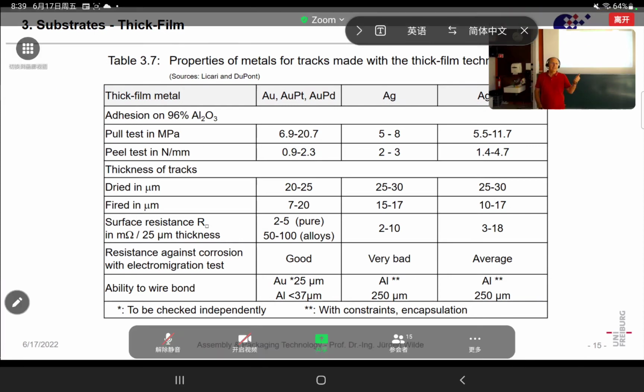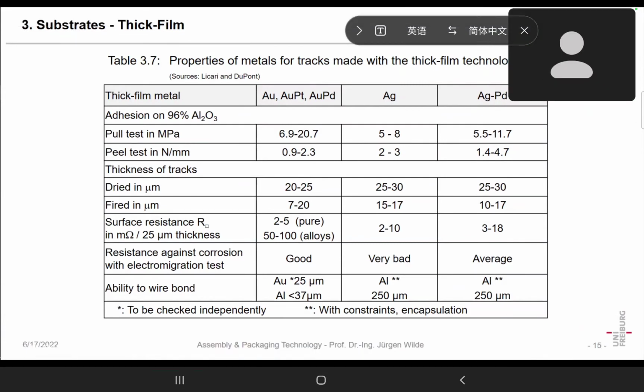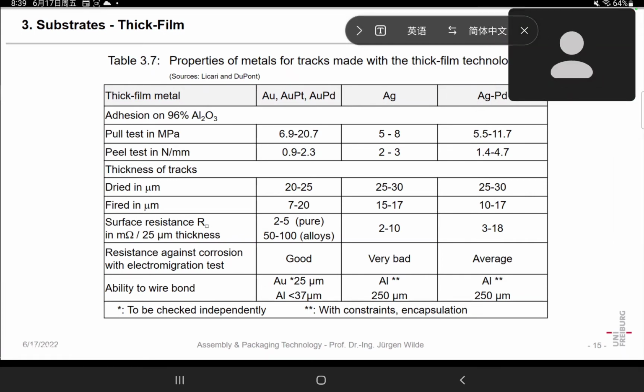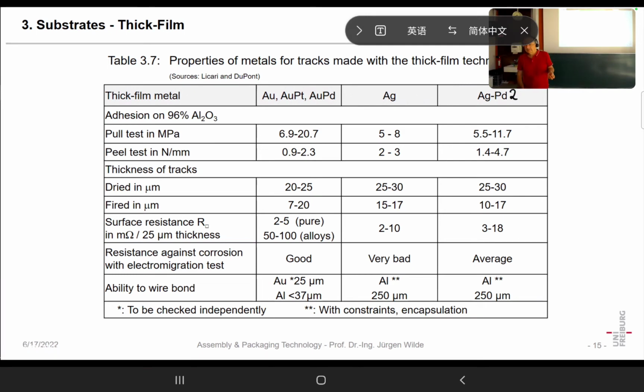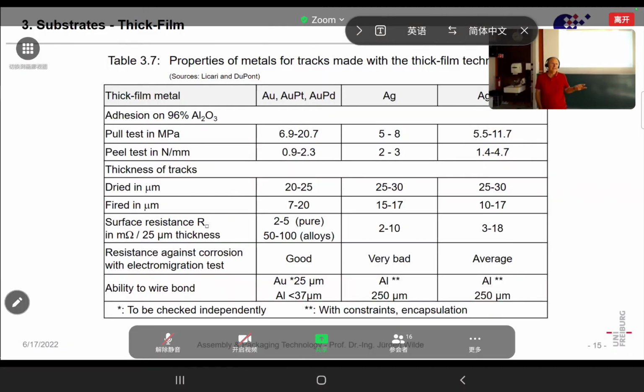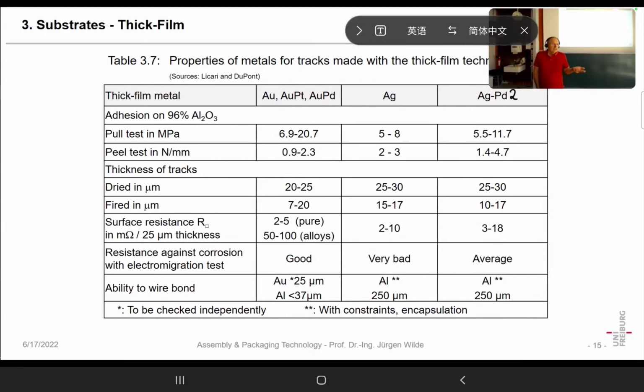Yes, cheaper, very good. And what is a disadvantage? It is corrosion. It can react. Yes, the disadvantage is copper oxidizes. Copper is not very corrosion resistant, and it is not resistant against high temperature air. That means at 850 degrees centigrade, which you would also need for sintering, it will just be converted to a black powder that is named copper oxide.